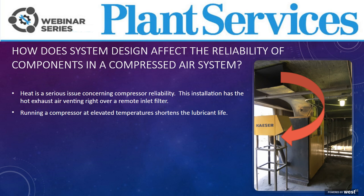You have to remember that the compressor lubricants are all based, the time that they can run is based on 180 degrees Fahrenheit. So if you buy an 8,000 hour compressor lubricant, that's based on running 8,000 hours at 180 degrees F. Every 18 degrees over that you run the compressor, you reduce the lubricant life by about half. So an 8,000 hour lubricant becomes a 4,000 hour lubricant.